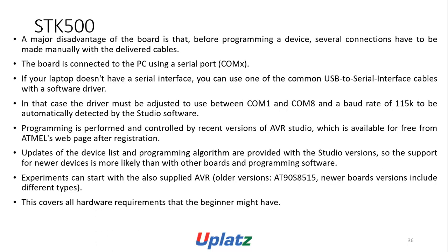If your laptop does not have a serial interface, you can use one of the common USB to serial interface cables with the software driver. In that case, the driver must be adjusted to use between COM1 and COM8 and a baud rate of 115K to be automatically detected by the studio software. Programming is performed and controlled by a recent version of AVR Studio, which is available for free from ATMEL's webpage.